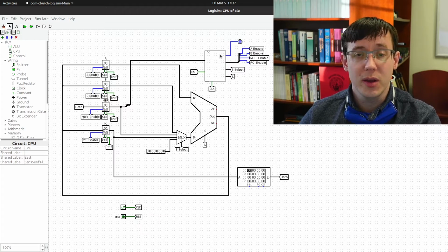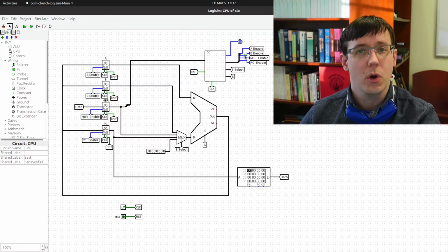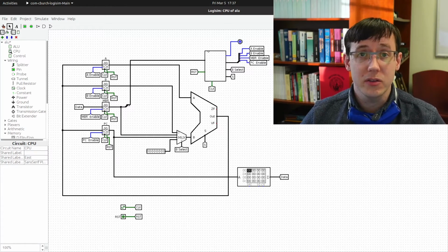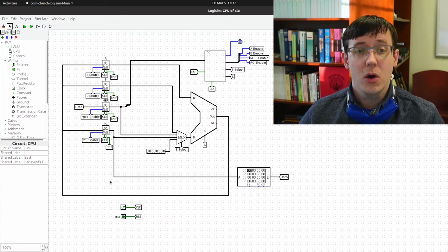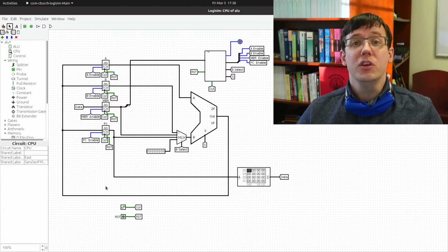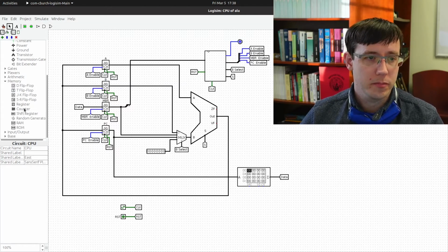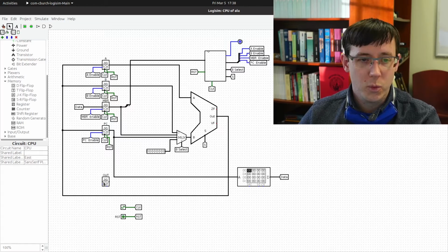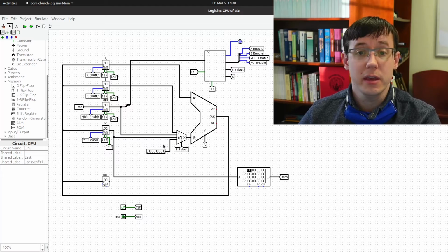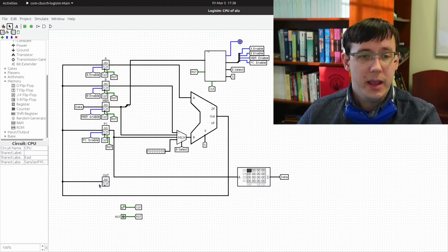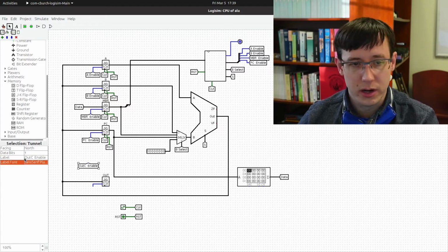And so we will be able to see when our program completes by this halt pin going from 0 to 1. And the last thing that we want is the ability for our CPU to produce some output. So let's add one more register that the CPU can write to in order to produce output. And we can make it writable by connecting it to the ALU output. And then we need to give it an enable, and we'll call this tunnel out enable.